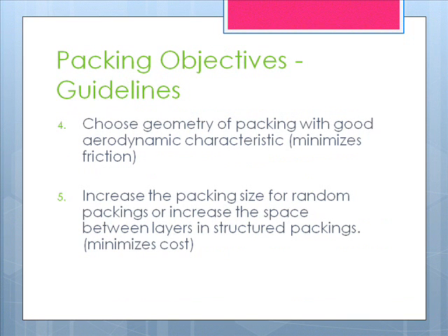Number 4, friction must be minimized by choosing a geometry of packing with good aerodynamic characteristics. And lastly, number 5, the cost must be minimized by increasing the packing size for random packings or increasing the space between layers for structured packings.